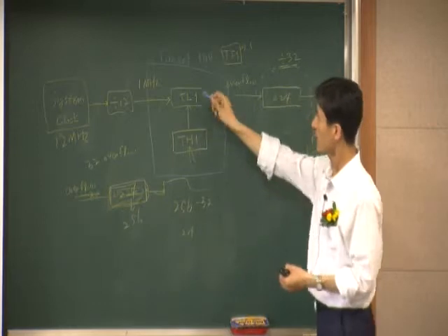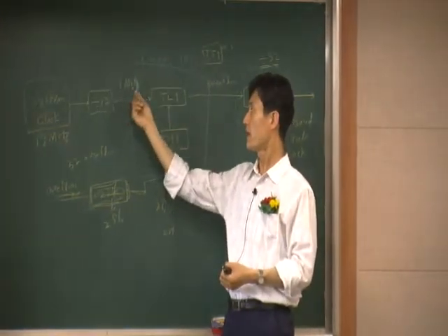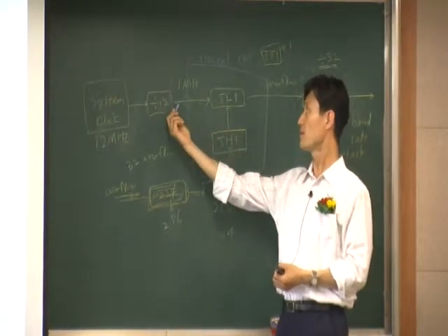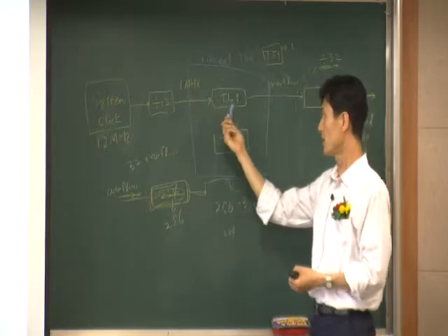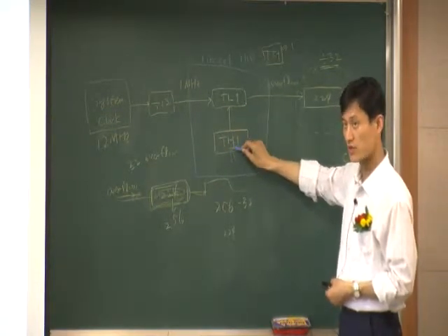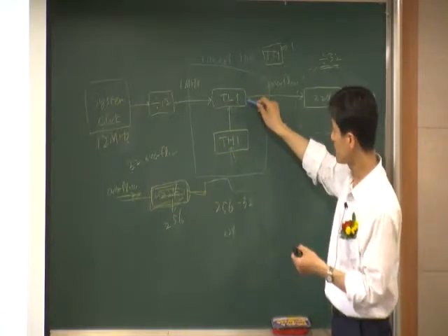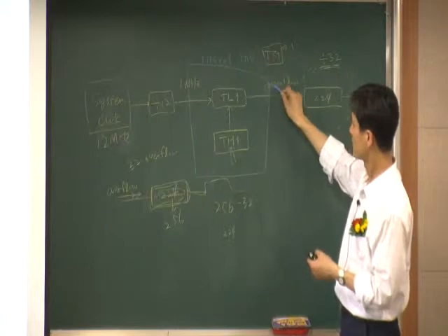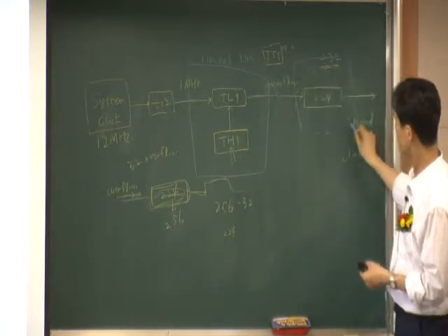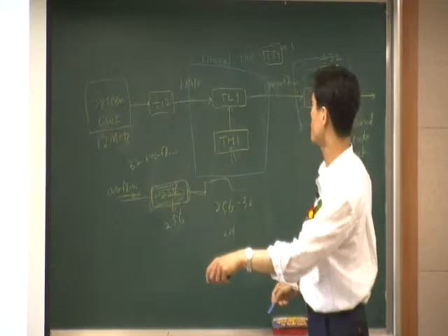So inside the timer hardware, we are getting the input of a 1 megahertz clock. This 1 megahertz clock is coming into the timer as an input. And based on the initial value you program, whenever this timer overflows, you get an output. And this output now goes into this hardware, which is the divided by 32 hardware.